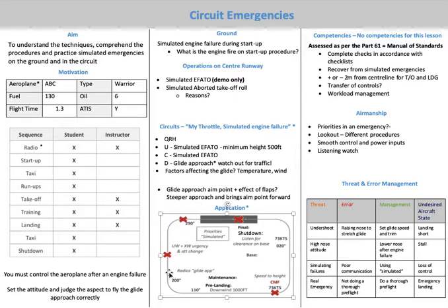And then on upwind, make sure you've got that rapid attitude change, and because we've got that high nose attitude, there is an error. The management technique will be to lower the nose after engine failure, and the undesired aircraft state will be stalled. So the error would be not lowering the nose. So make sure you lower the nose as well, set that glide speed 73 knots, and you trim as well.